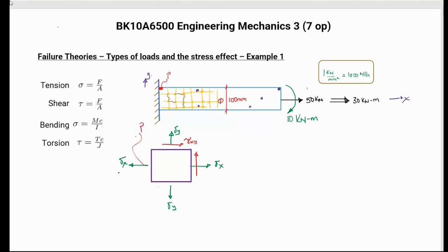And then just to write it once, because there's no point writing the name four times, this should be to keep consistency with the reciprocity of shearing stress. So this should be like that. Then the question is, okay, now guys, how can I come from this part to this part here? You say, okay, let's take this load here. This load is producing tension on the element, meaning that it's producing a normal stress.